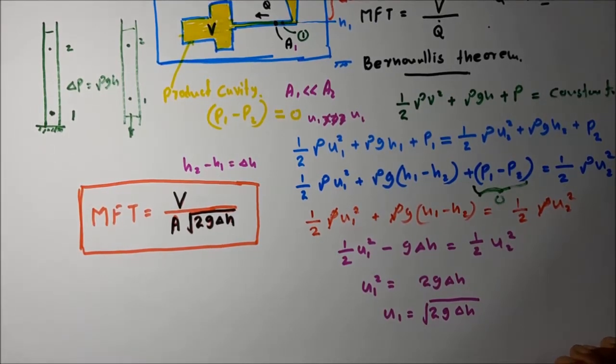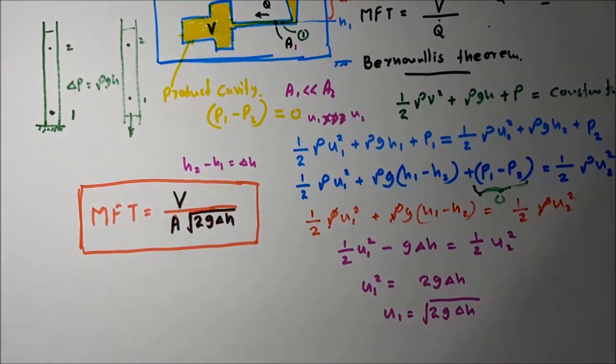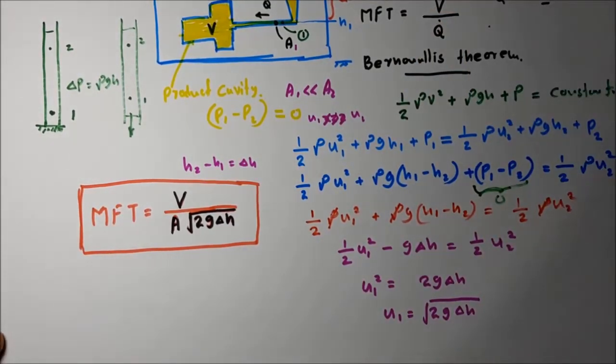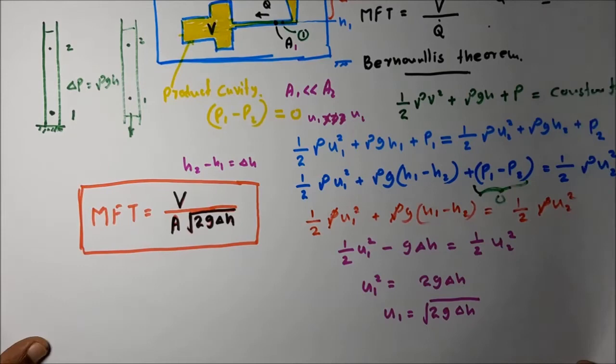This calculation is very important. We are ensuring this mold has filled completely by looking at this mold filling time. If it takes less time to fill than this calculated time, that means the mold has not completely filled with the molten metal. Okay, this calculation is very important.